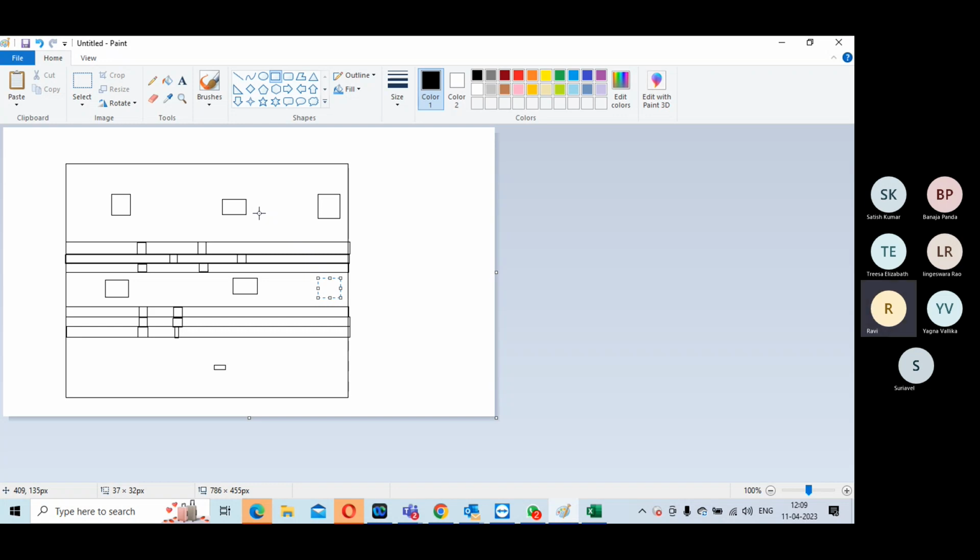No, you don't have to make it exclusive. Other cells can sit there, but standard cells should sit there, and your spare cell should sit there. Don't make it exclusive. This is a hard bound for spare cells.